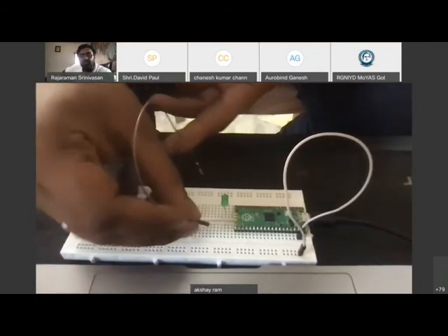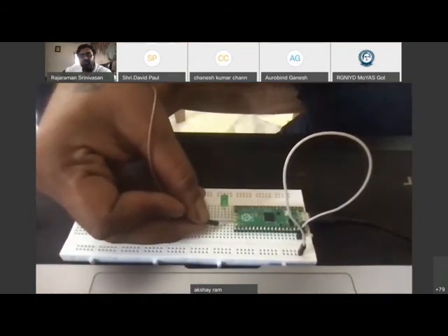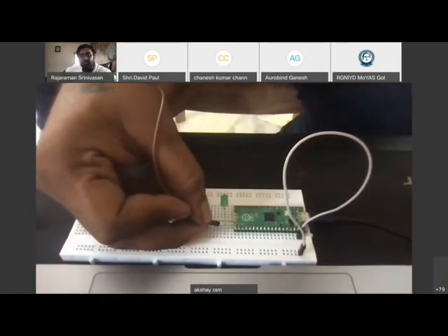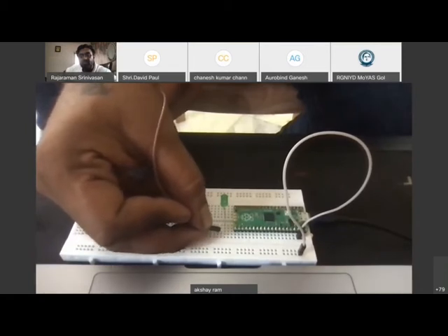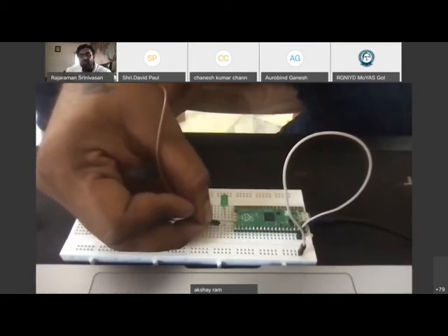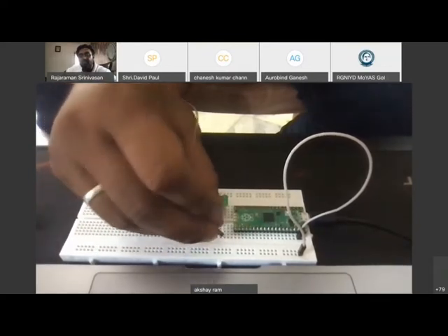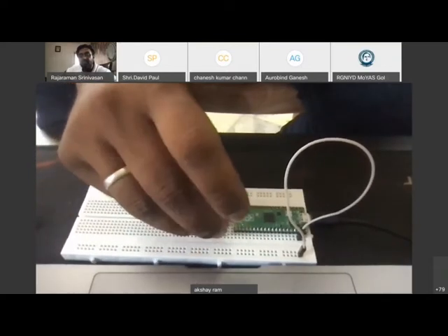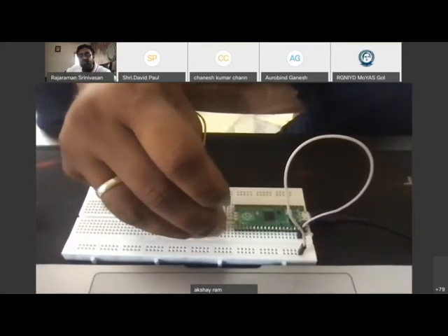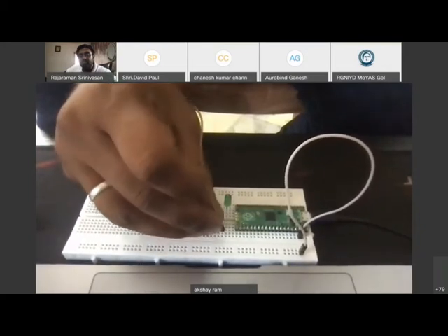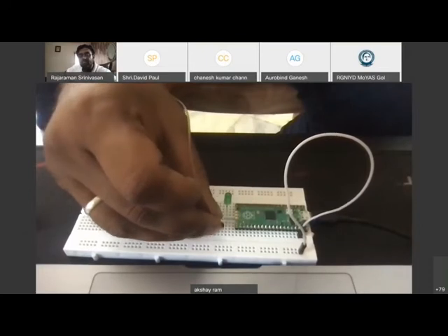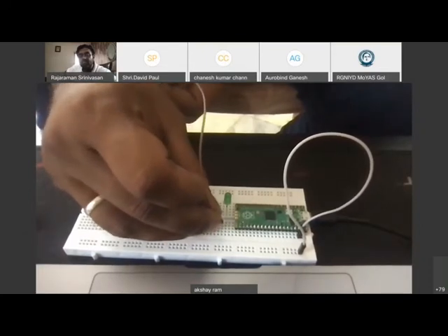Now that this cathode is connected onto this edge of the breadboard, all of these connections, as I had shown you in the video, are now all connected to this leg of the LED. So if you take the connection from here or here or anywhere on this, it doesn't make any difference. It's all the same because they're all connected.